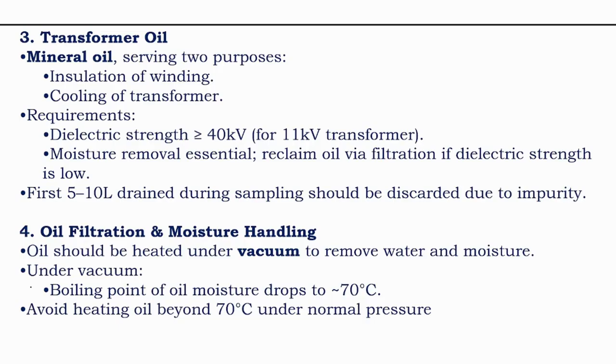While testing, we have to collect the oil from the drain valve. The first 5 to 10 liters we need to remove. You should not take it for testing, because there will be some moisture content at the bottom of the tank, since the water density is more than the oil density.